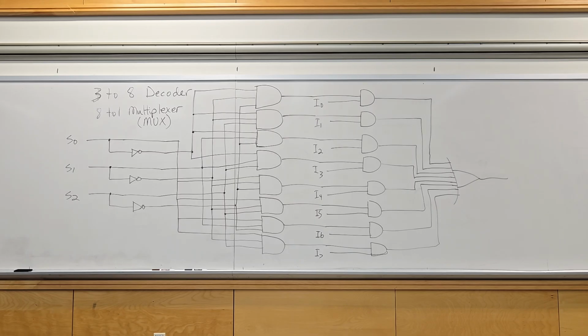These are frequently used in ALUs, arithmetic logic units, where your arguments come in and all the calculations, addition, subtraction, multiplication, etc., AND, OR, exclusive OR, whatever, come in, and the function for the output is selected by giving it a binary number. All of them get calculated, but only one of them gets selected to go to the output.